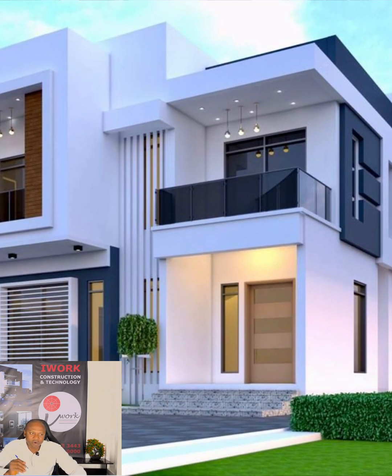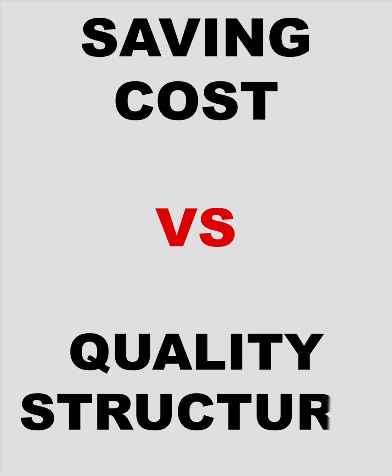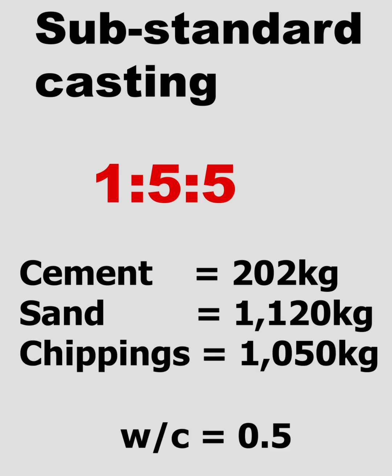Eurocode 2 and BS 8500 British standard. These two standards are complementary and widely accepted across Europe and Africa, including Nigeria. So, let us see the cost savings in mixing a weak substandard concrete against a strong standard design concrete that complies with international building codes. The most common weak concrete mix across Nigerian building sites for one or two-story building is 1:5:5 by volume.